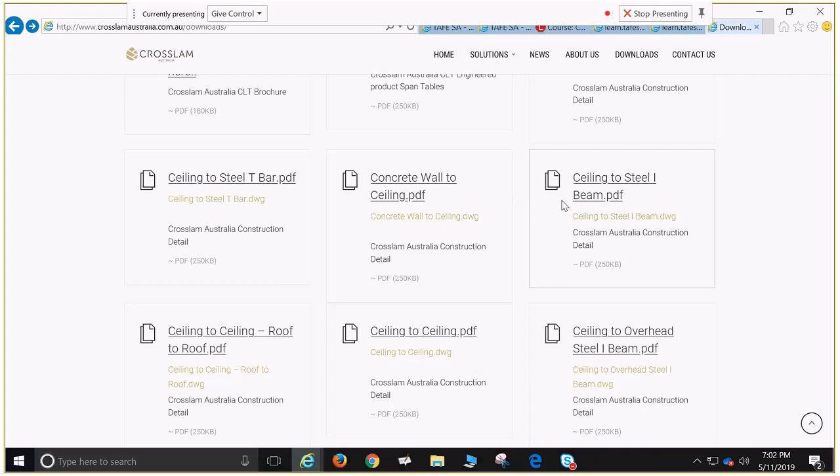But also, that's very important information if you're glazing elements underneath these things. So we say, okay, within that span table, it tells us what our live loads can be and what the resultant deflection is going to be from those live loads, and then you can look at your occupancy or what the intended use is and say, this is our maximum expected live load.